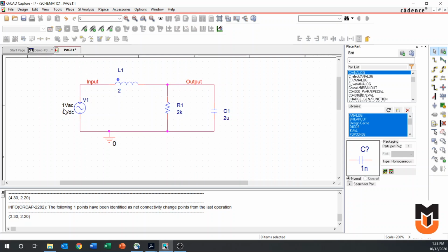And for right now, I'm going to leave the magnitude of my AC voltage at 1. The reason that is sort of an attractive thing to do is, remember, our transfer function can be used to get our output from the input. So we can say our output, Y, is equal to the transfer function times the input, so H times X.